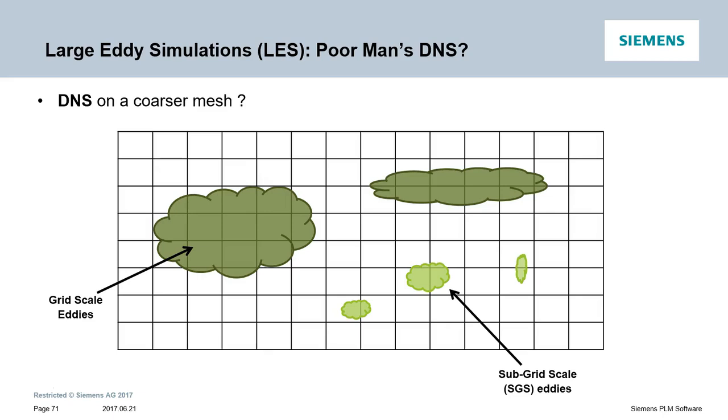But in reality, there is an interaction happening between all scales of motion all the time. So the results for the larger scales would generally be wrong without taking into account the influence of smaller scales. Now, if we could somehow magically account for this missing information, we can run a poor man's DNS, or more formally known as large eddy simulation or LES. And the models that account for this missing subgrid information are called subgrid models.